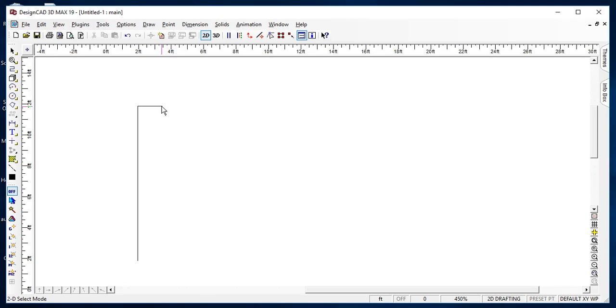Now the window that we have is next, so we're going to get the Ortho Line Drawing tool, right click on this section here, and let me just do a quick calculation here. We have a total of 13 feet, and we are subtracting 5 for the middle, so that means that these windows are each 2 foot 6.